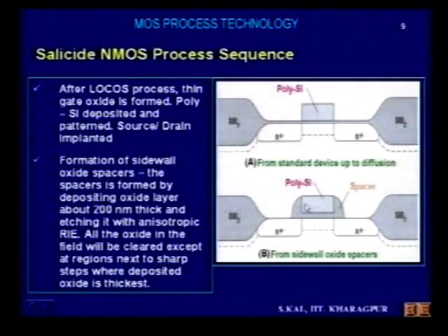If you etch back, from here it will etch back, here it will etch back, and the same thickness will be etched here. And as the thickness at the sidewall space is more than the thickness here and here, it will remain. So that means this polysilicon is totally covered from three sides by oxide. Bottom is gate oxide, and these two sides are spacer, and that spacer is again oxide spacer. Okay, so this oxide spacer is formed.